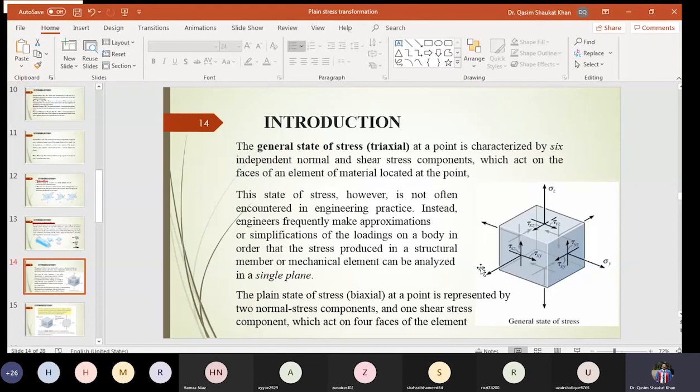So in this case, normal stress sigma xx is acting along the x-axis, and this stress will produce elongation, because it is positive. It is trying to elongate the element. This is sigma x, and the complementary of this sigma x is this stress. Complementary means it's the same stress but with the opposite sign, acting in the opposite direction. Magnitude is the same.